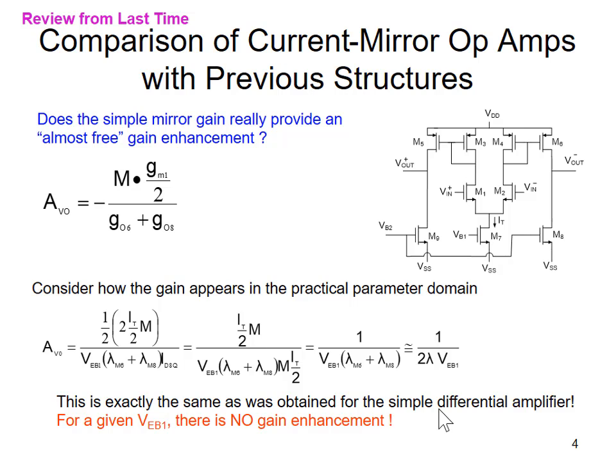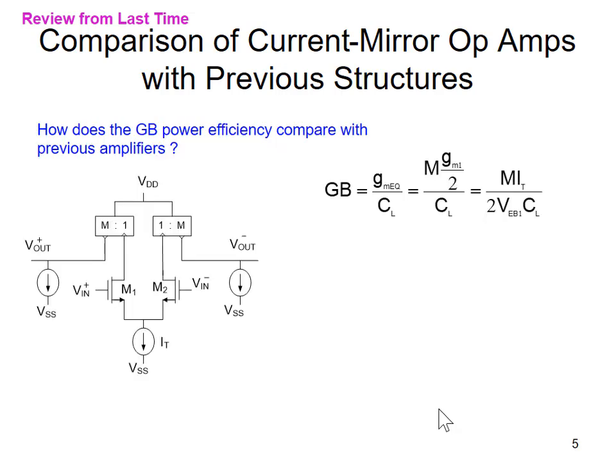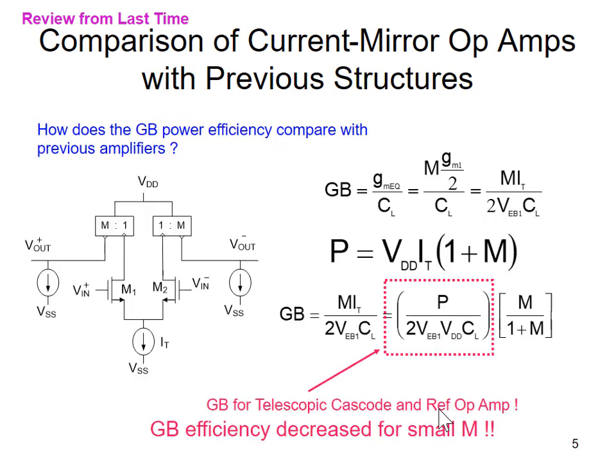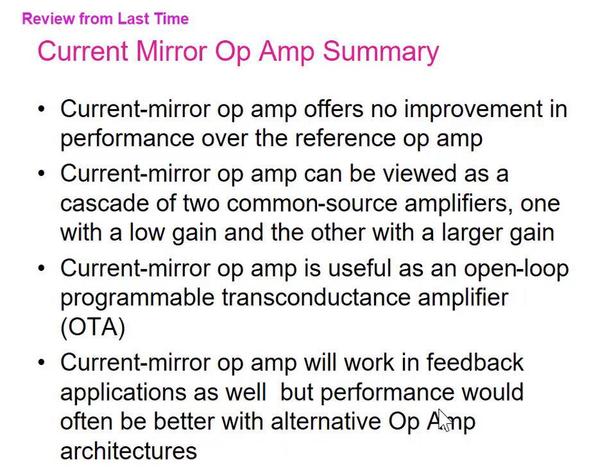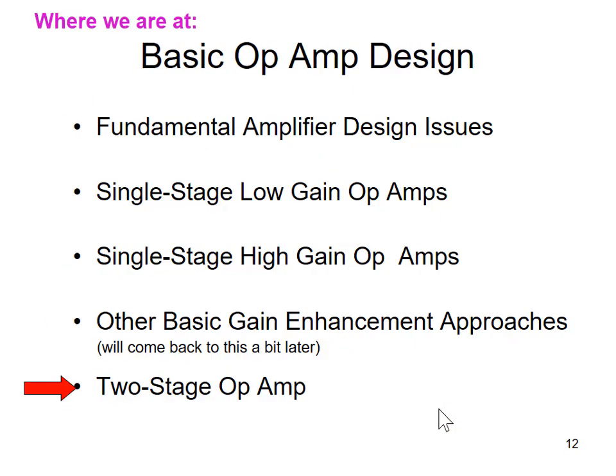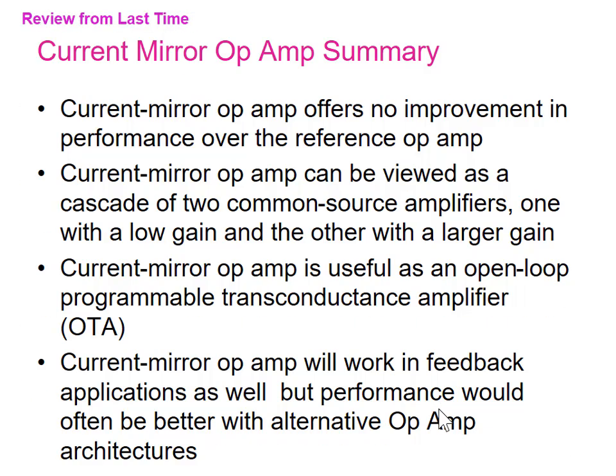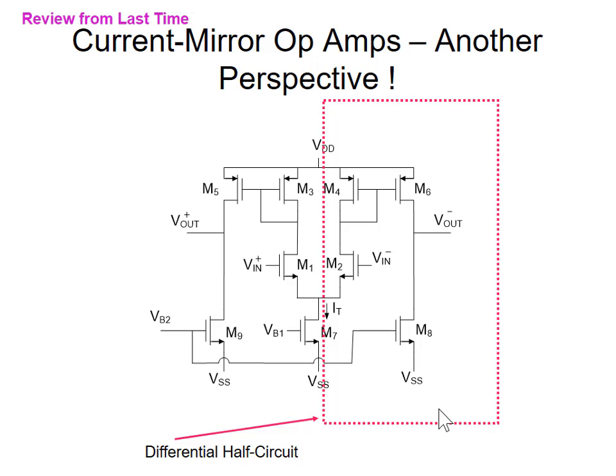No, not this one, excuse me. So I'll do this wrong again. So this is with the constant current source bias. And then the other thing we did was put, do I have the mirror on the bottom? No, I didn't have the right slide. So if we want to convert this structure to a current mirror on the right side and lose this one output, we take this terminal here and just tie it around to this point here.